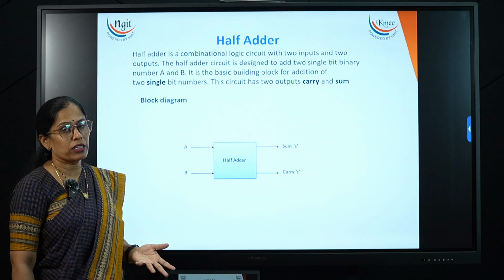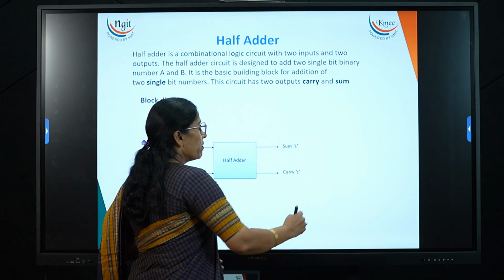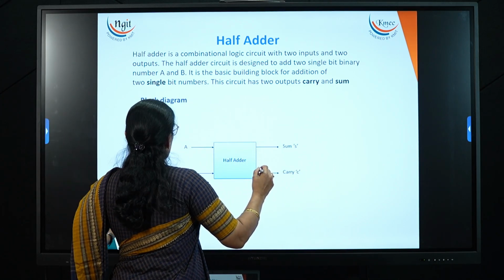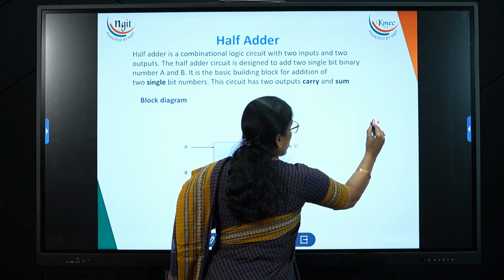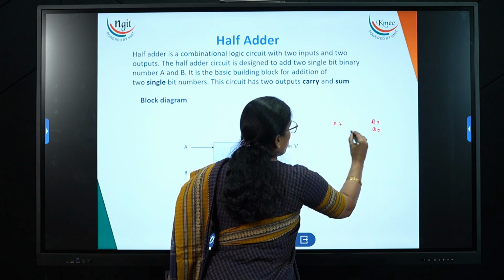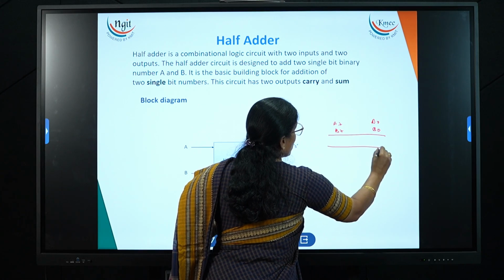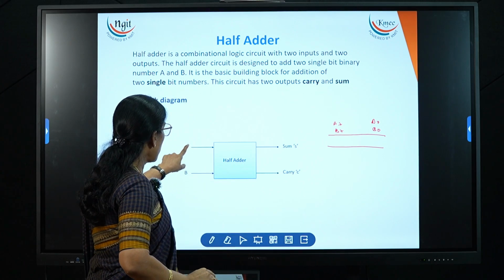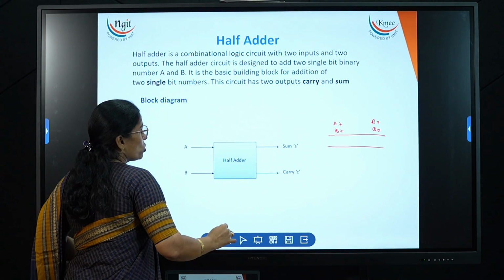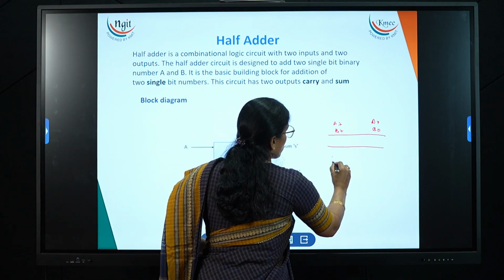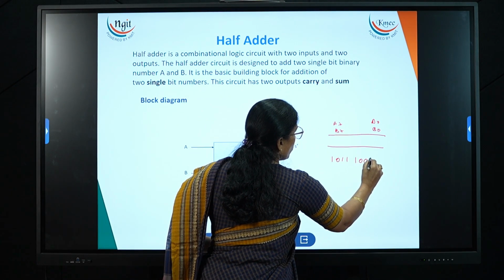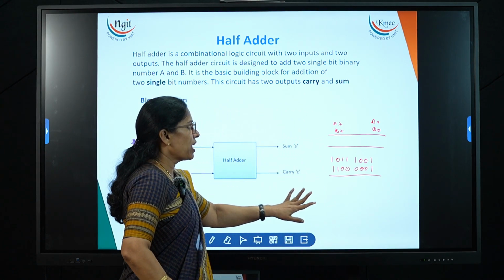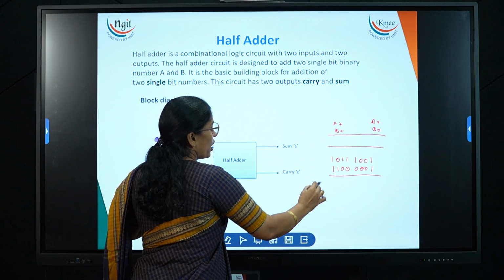Now if I wanted to add 8 bits at a time, then we need to add like this. So here I am taking two 8 bit numbers, A0 to A7 and B0 to B7. We need to take the values and it will give the sum from S0 to S7 and also the final carry. Here it is adding only two binary values at a time. So if I am adding 8 bits like this, 1011, 1001, 11000001.